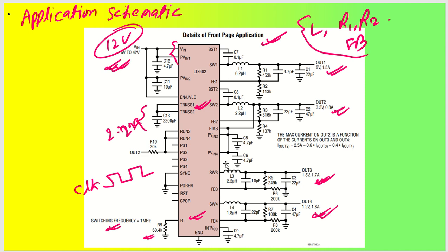All these pins are going to have their proper inductors, and these feedback pins are going to have a resistor divider design so that you can regulate your output voltage. The output capacitor must be taken into account properly so that it can drive the load without any ripple or noise. Okay, so with this information we'll directly get into the designed circuit that we have done.